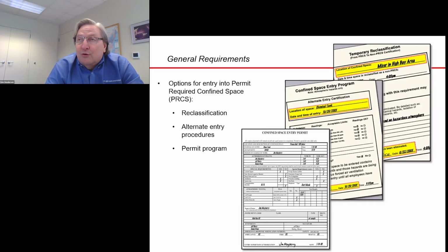A lot of programs are built around use of the alternate procedures. The alternate procedures allow you to do solo entries. They allow you to have an entry that does not require a standby safety watch or a rescue team. When it's appropriate, it's a way to streamline your confined space entry procedures and yet maintain safety.